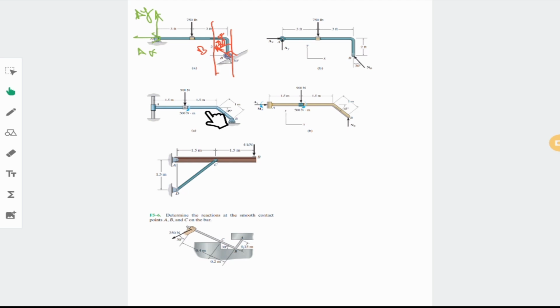And the same story here. Don't consider the whole mechanism, just a small piece of that, and try to do motion. If I have a small piece here, meaning that I have a roller, a beam connected to that, and let's forget about the rest, you can do rotation. It does not prevent you. That's why we don't have M here.